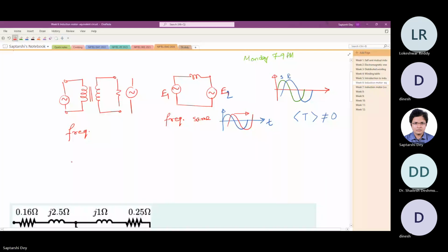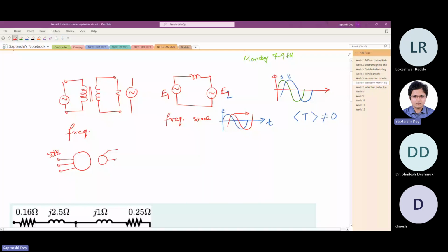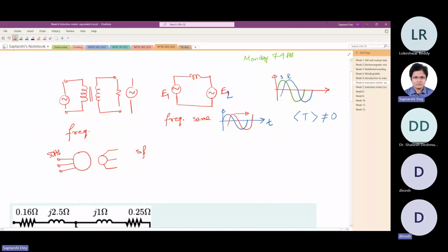Induction motor, stator, that is connected to the, say, grid connected induction motor to the grid. So it is running, the stator circuit is working at grid frequency, let us say 50 Hertz. Whereas the rotor, when it is rotating, it has some other operating frequency, which is sf. So two electrical circuits operating at different frequencies, and there is power flow between them.